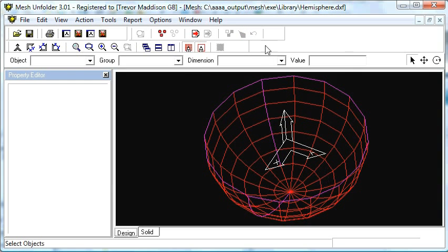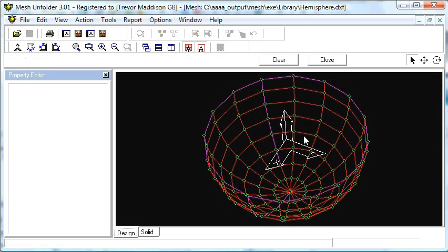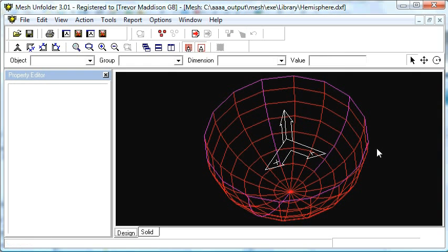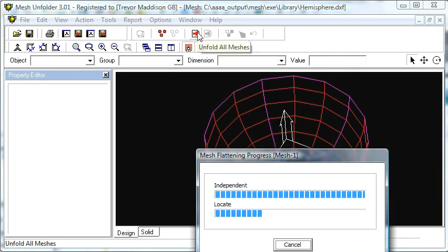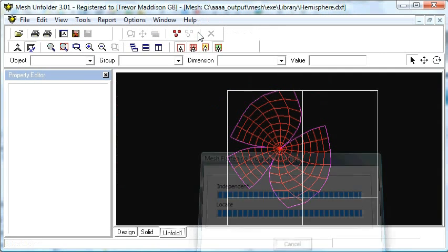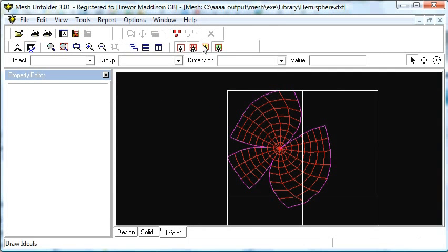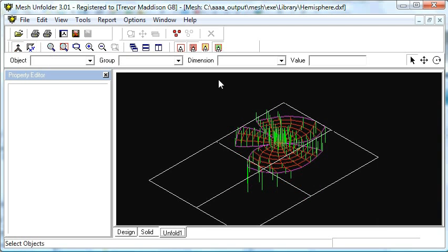Let's create another one of those by selecting the design, again node mode, and split from there to there. Tell it to split, and now if we unfold we have a different result with less stress in it. So if we look at the 3D view, the strain indications have gone down, showing the effect of putting darts in a design like that.